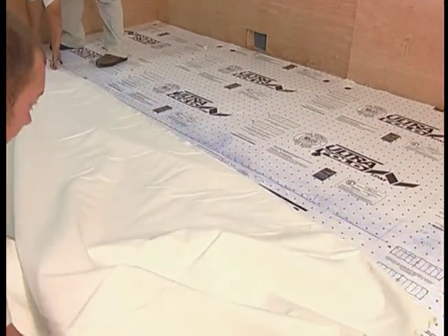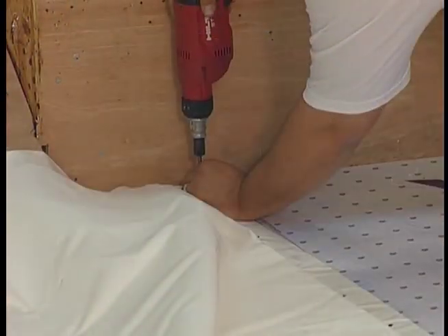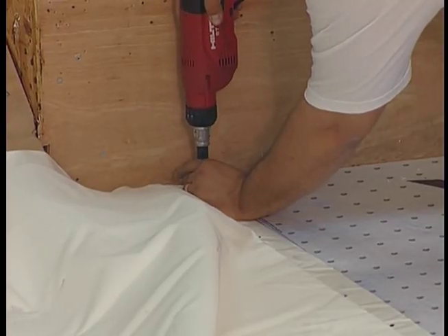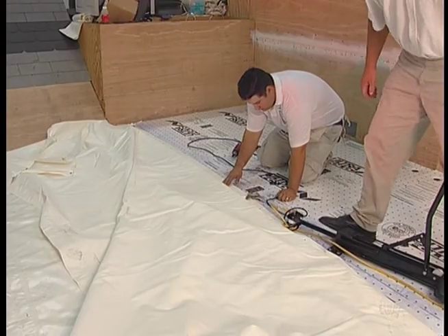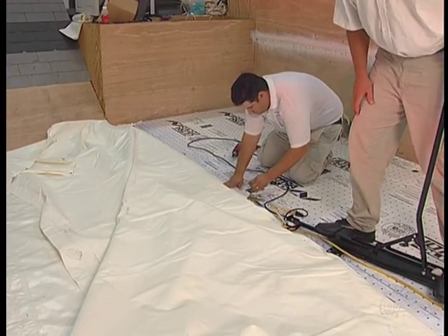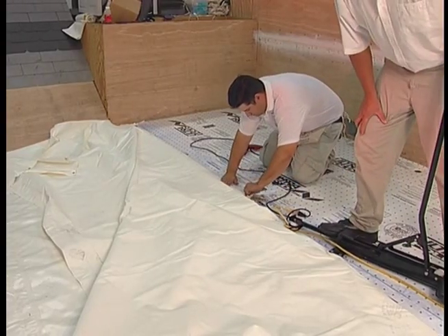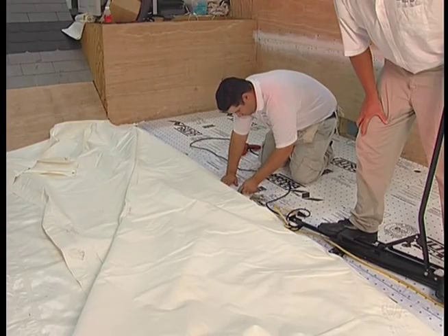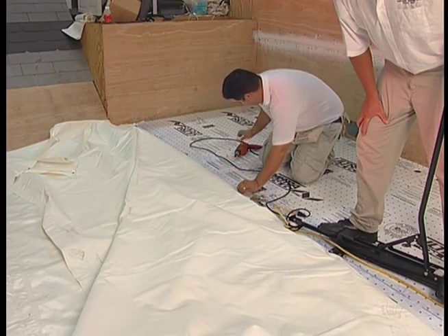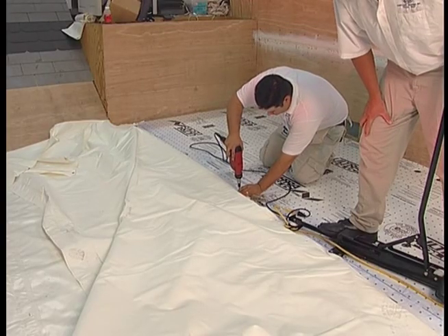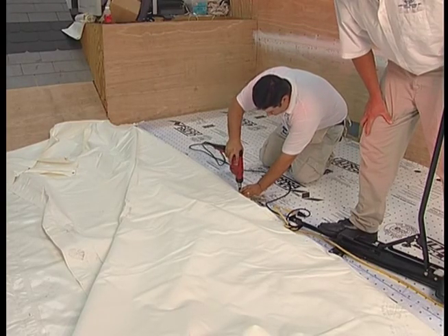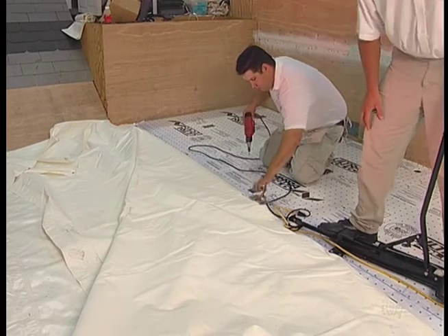Position the edge of the first tab with the chalk mark and install a Duro-Last plate and fastener near the end of this tab. Position the grip pole about 5 feet from the first fastener and pull the membrane tight and straight along the chalk line. Install another fastener about 6 inches from the grip pole. Continue across the roof in the same manner